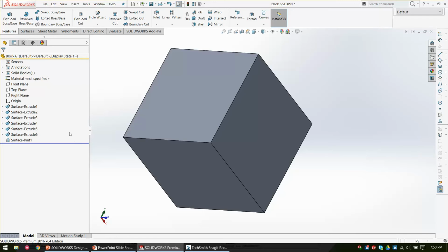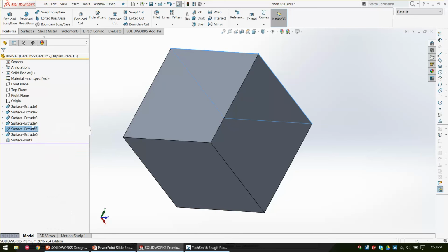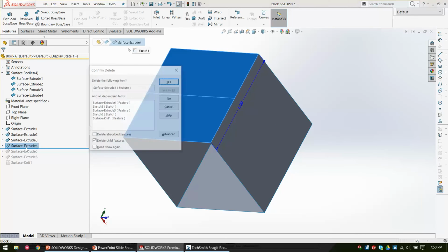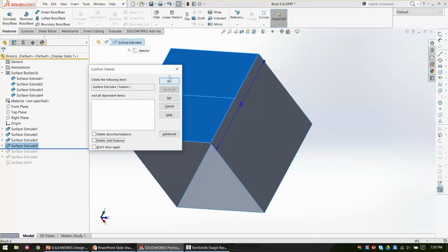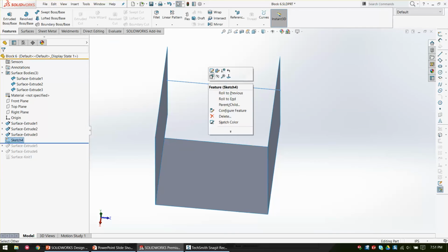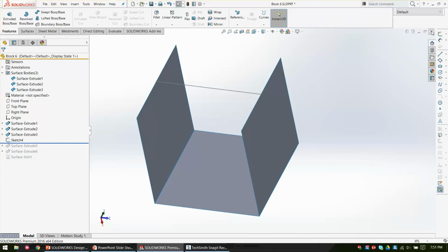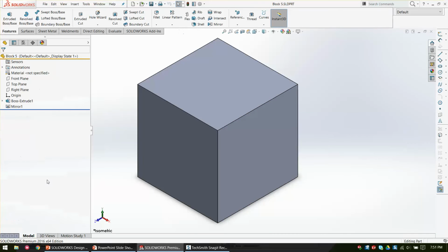But at any time, I can totally roll back and say, instead of this feature, I want to use something totally different. And I could modify our sketch and put in some sweep or loft, put a lofted surface in there instead. My knit will still work after I reselect my new surface, and I would get the exact same block with one side just totally organic, messed up geometry. So this could be really good design intent based on what you're trying to accomplish in the end.